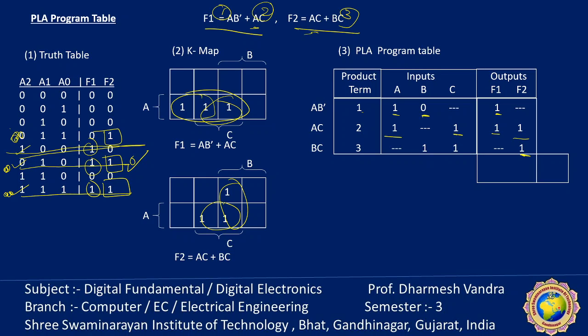Programmable PLA means that we specify the path of the AND or invert pattern. It consists of 3 columns. The first column lists the product term, symbolically or numerically. Here it is shown numerically, in terms of variables. The second column specifies the required path between the inputs and the AND gate. And the third column specifies the path between the AND gate and the OR gate. This is between AND and OR gate, and the second column is between the input and AND gate.